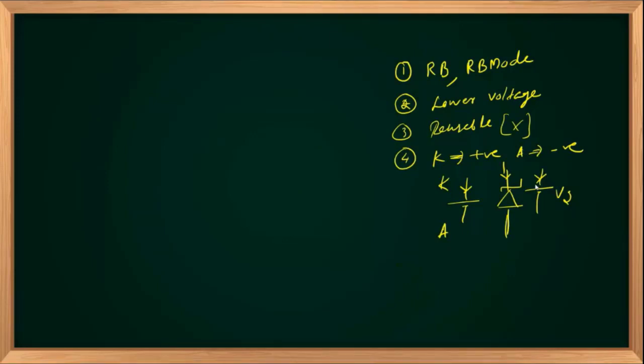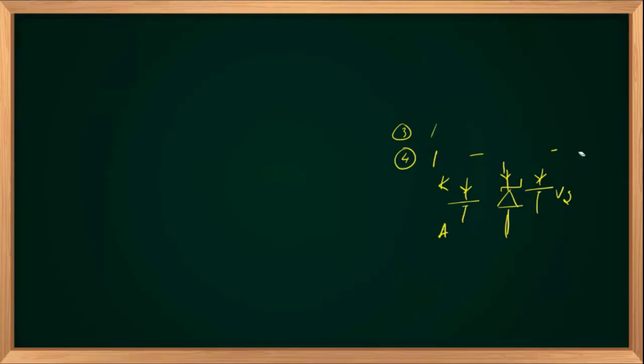Right. Okay, thank you. So these are the 1 mark or 1 word questions based on theory portions of your Zener and avalanche breakdown. Avalanche breakdown involves collision between atoms. The highly accelerated electrons will collide with atoms and generate multiple electrons. All those electrons will again accelerate in the high electric field and again collide with atoms, and multiple collisions will increase the number of carriers, which will increase the reverse current. Finally, high velocity carriers collide with the atomic structure, then the atomic structure also gets disrupted, so the diode loses its electrical properties. Right.